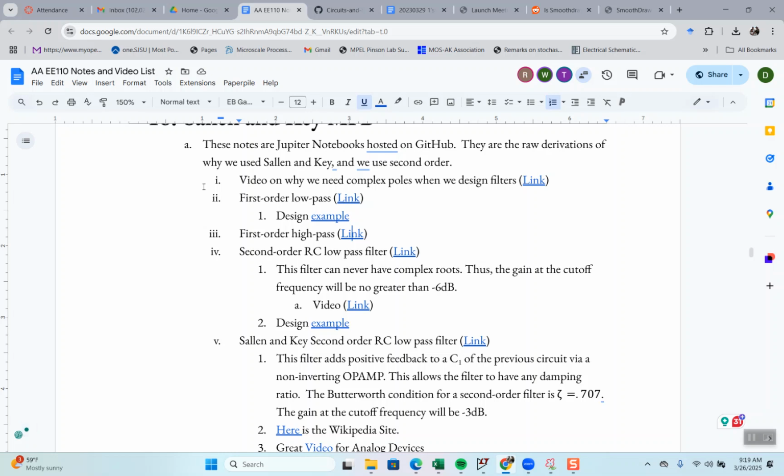Or you're in a meeting, let's call it the robotics meeting. And yeah, we've got a problem with the noise on the sensor. Like, okay, what are we going to do about it? Well, let's see. Do a low pass filter, but how much noise is getting through? Oh, this amount, this many dB. I think I need a second order. All right, what are my constraints on the board? Well, you really only have this amount of space. Okay, I can only use one op amp. And you can think about it in that way.